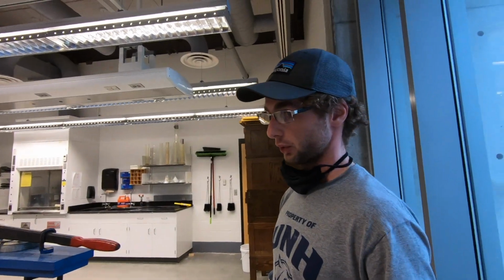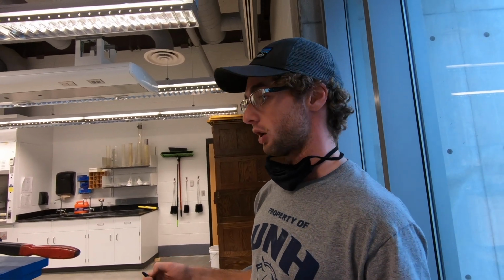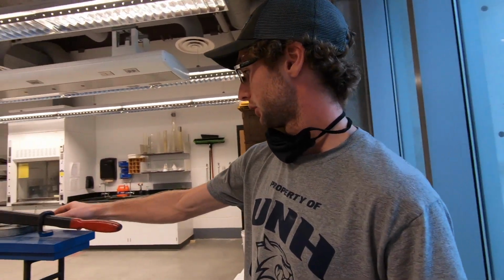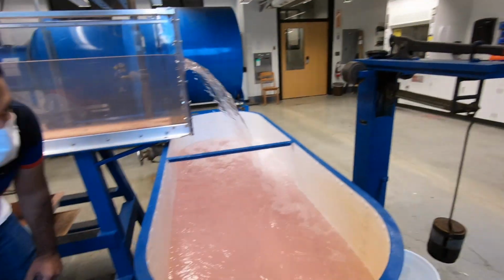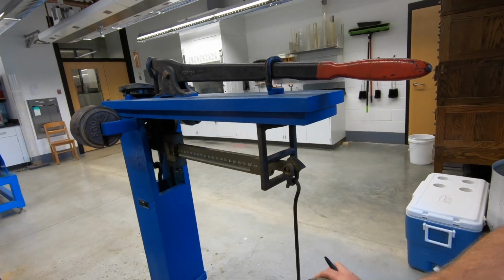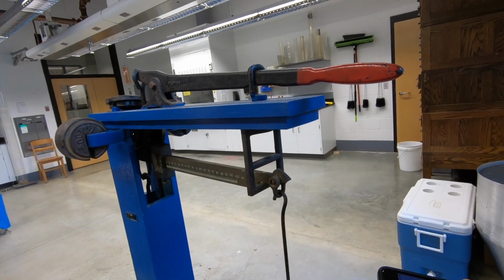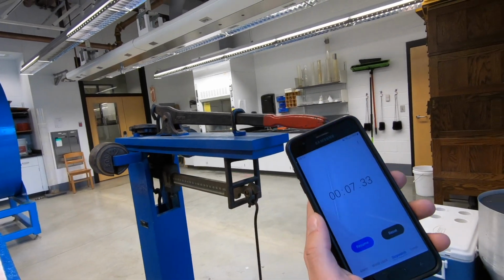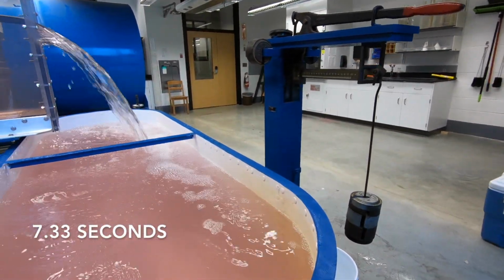After that, we're going to wait until the tank again equals the weight on the scale, at which point we'll know how long it took for the water flowing from the flume to weigh 200 pounds, and be able to use that to find a mass flow rate, and we can use that to find a volumetric flow rate. So, Roosevelt, whenever you're ready. Alright, we're starting. I'm going to add the 200 pounds. And boom. It was 7.33 seconds to add 200 pounds of weight.